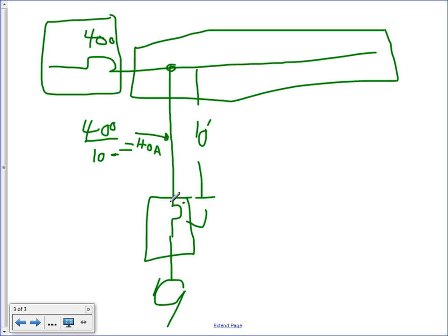Let's say the lugs here are rated for 75 because everything is 3-phase, and my conductors are THHN. Would that be number 10 or number 8? Can you guys go to Table 310.15(B)(16)? I can't remember if number 6 will cut it.